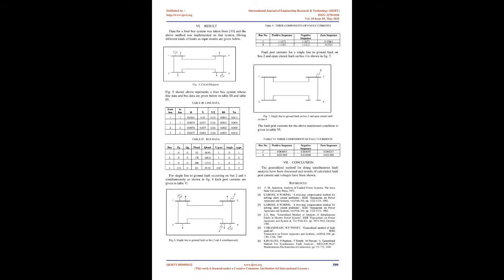Fault port matrix. In 2, although the short circuit fault was occurring, during simulating it the impedance matrix, i.e. Z bus, was used unchanged. But usually we cannot consider it like that as the fault may occur at any point on the network. Always considering a fault point as an addition of bus may make the calculations difficult. Hence Z. X. Han has devised the method of fault port matrix, which is easy to understand and lessens the computation time as well. Fault port matrix elements.